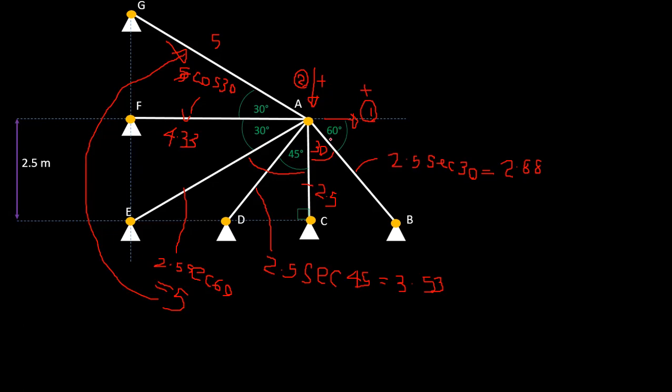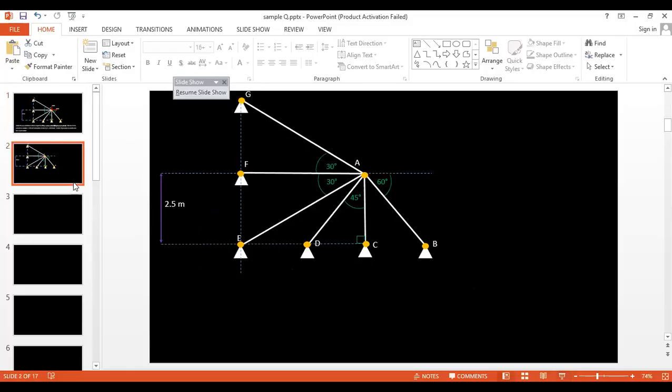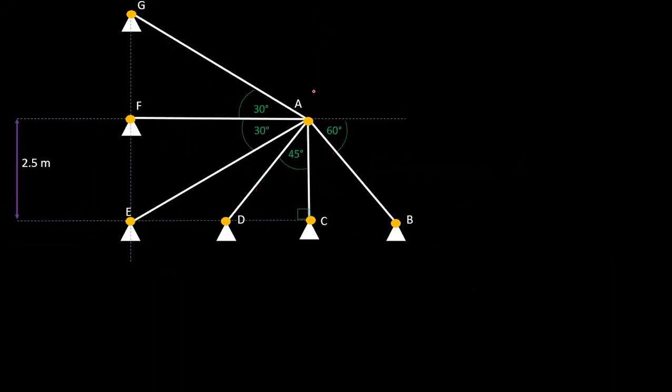As you see before, there will be some actual displacement. There will be a 60 kilonewton load here, and here will be 40. So there will be some displacements. What we did was set those unknown displacements to 0. So what you have to do is bring a fixed support to here. Just here we fix it.